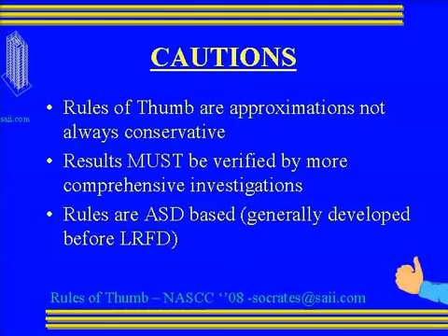Finally, the rules of thumb are based on allowable stress design, because they were developed long before LRFD. During the years when AISC was pushing LRFD and LRFD only, we got a lot of pressure to change these to LRFD, and I started trying to do that, and my numbers instead of 5 and 3.5 ended up being 6.8, and then I wanted to make that a 7, and it didn't work. So we resisted it long enough until in 2005, and thanks to Mr. Jim Fisher over here, we now have LRFD and ASD together.